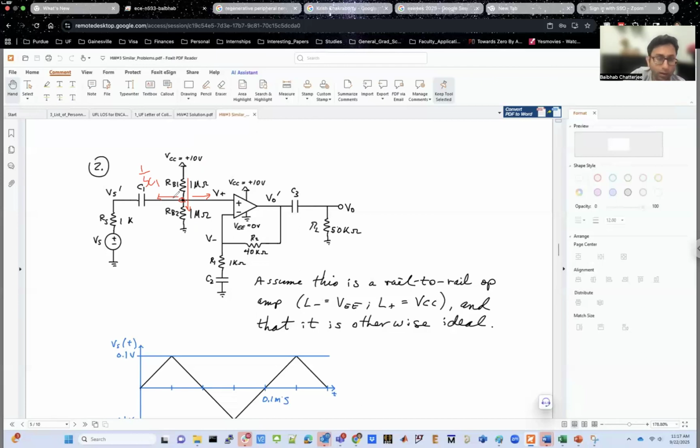Okay. So that's the reason why the voltage at this point is going to be VCC over 2. Now that is exactly half of your maximum voltage and minimum voltage. That's exactly what you wanted to have as biasing point for your op amp. So RB1 and RB2, and the subscript B stands for biasing in this case. So these are biasing resistors which are making sure that the input DC point of your op amp input is 5 volts.